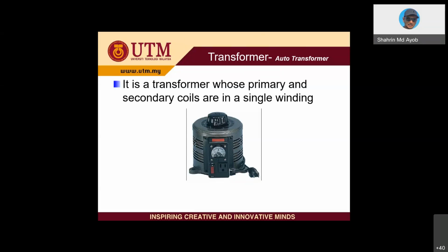Inside that machine lab, the power supply to the machine, the induction motor, is a fixed 415 volt. But in order to see the performance of the motor, we need a variable input voltage to the induction motor. So we use what we call an auto transformer, or sometimes popularly known as a variac, meaning variable AC voltage. It depends on the capacity. For small voltage you can have a very small size, but for high voltage, for example 450 volt, you will have a very big auto transformer.